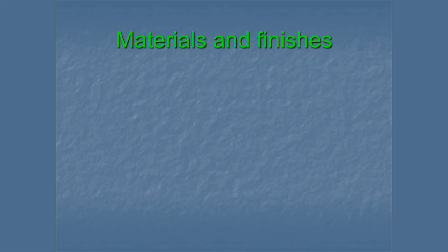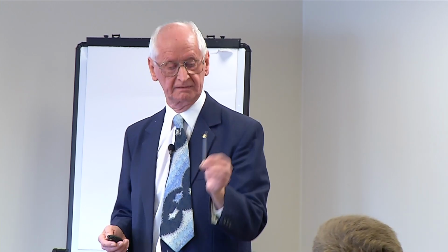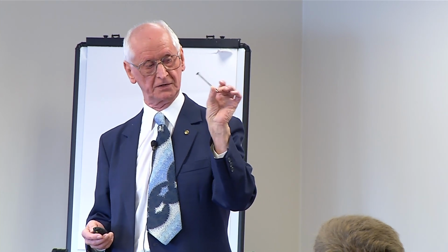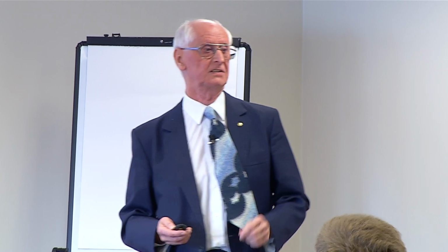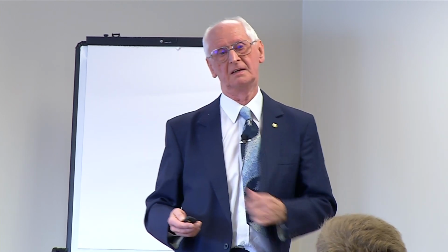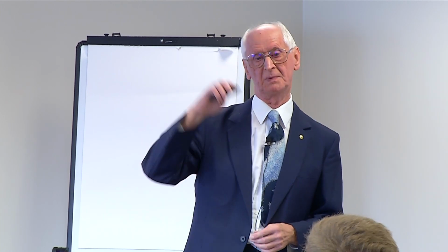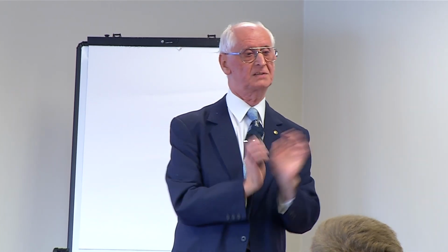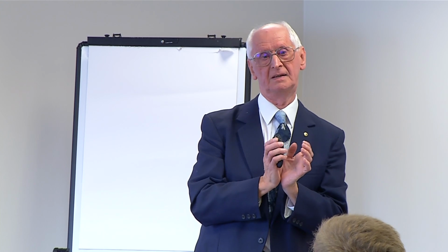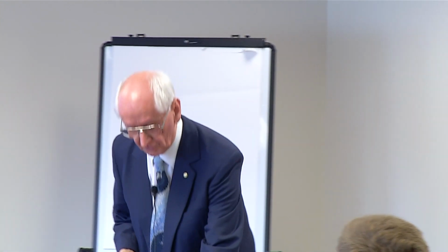Right, let's look at materials and finishes. Plain steel. So, cadmium plated steel. Now, if you look at these afterwards, you'll see that's just a plain steel nail, round wire nail. You do find fixings which are cadmium plated. Now, cadmium, as you know, is below steel in the series, so it protects by putting a coat over it. But it doesn't necessarily last that long.